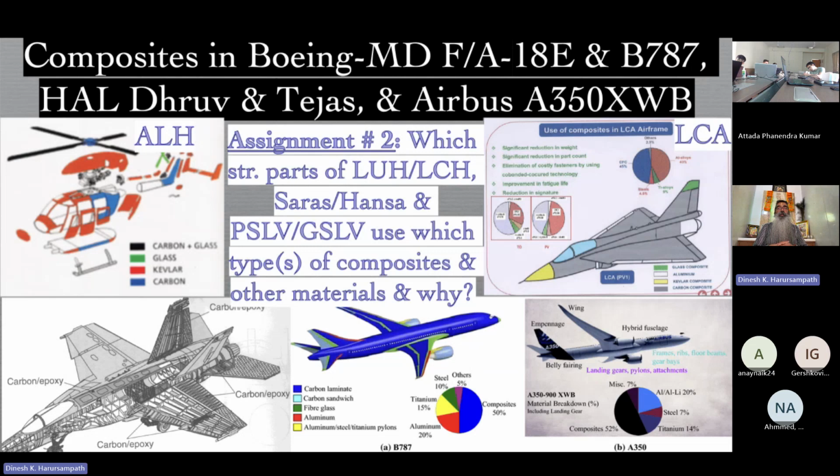And the requirements there are not only the two material properties that we discussed in the previous slide, namely specific strength and specific stiffness, but also how these change with temperature. Some of these properties are not constant with temperature. As you heat the structure, the material gets heated, and most materials will degrade with increase in temperature, so the higher temperature performance will be lesser. So obviously you can't use polymer matrix composites beyond a certain temperature, which is when you go to these other matrices.